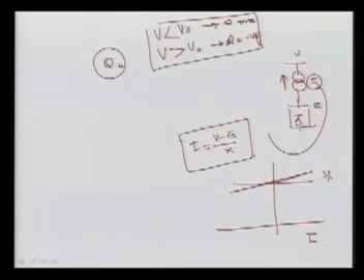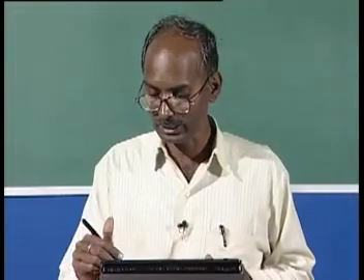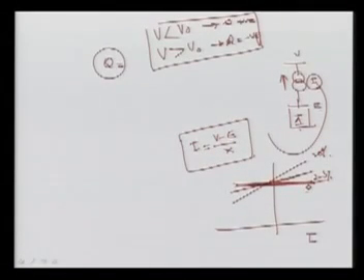As I said, if it is 0% slope, then the operating point is not well defined. For the same voltage, it will be oscillating, hunting. So we intentionally go for 5%. We don't want 2%, so 2 to 5% we can maintain. 0% is not desirable, however we can go for that. But in the natural characteristic, this slope is 20% because the reactance of the transformer is very high. So the I-V characteristic is related to the reactance of the transformer. So we normally go for such compensators having slopes of 2 to 5%.